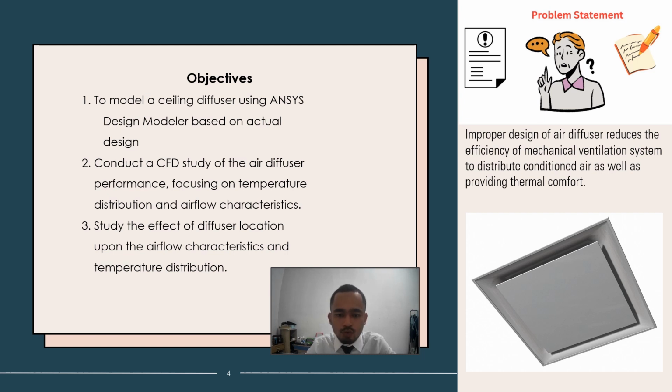Next, we will go to the objective. First one is to model a ceiling diffuser using ANSYS's design modeler based on actual design. The actual design that I have just mentioned can be seen in the figure on the right, on the bottom right, which is a plate type ceiling diffuser. So I will be modeling a geometry that resembles the actual device, and the dimension of the model will be according to this actual design.